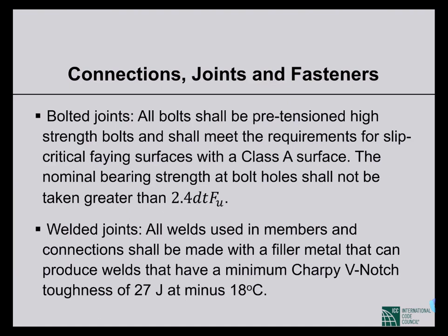AISC has a publication, most probably Appendix N of AISC 360, and there may be another AISC publication where all the pre-qualified connections are shown. So we can use those pre-qualified connections. If we want to use some other type of connections, then we have to go for all these tests and justify the use of those connections. Then they will be considered as pre-qualified.